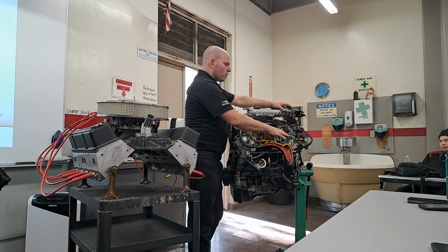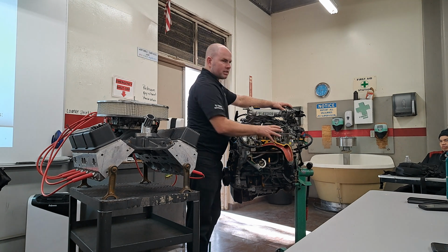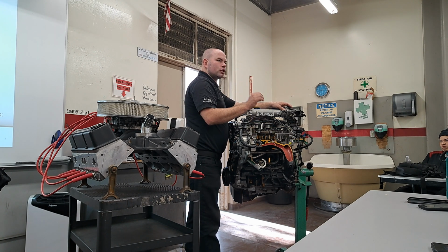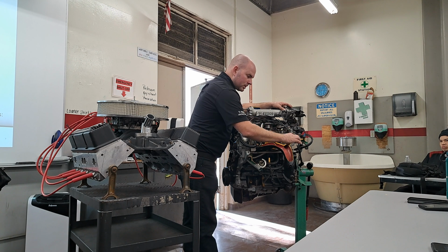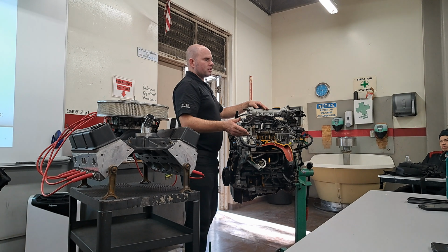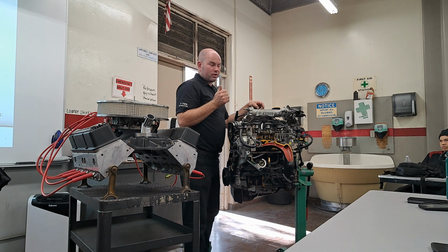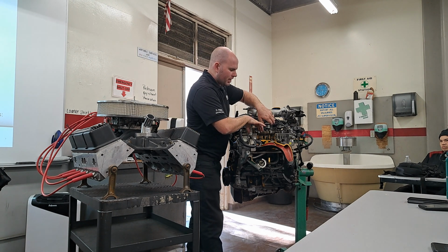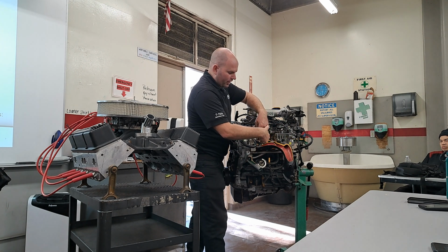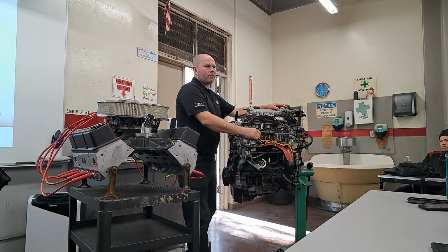A header, if you want a header, you get rid of this big cast iron thing and you make a thinner, lighter steel tube one, and the tubes would be separate the whole way, right? You pull 4 of them out. To increase your scavenging effect, like we mentioned a little earlier, you could take those headers and precision tune the length of the runners. So typically a longer runner is going to be better for low end torque.